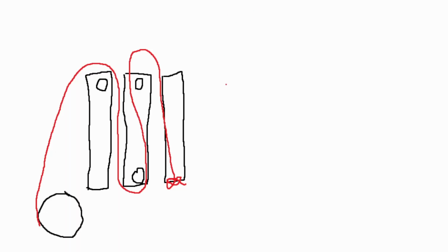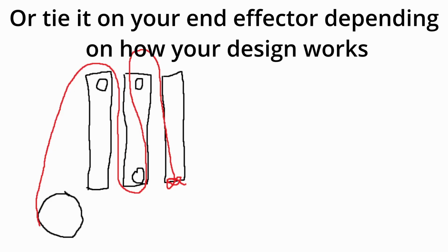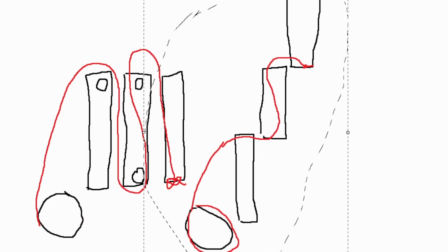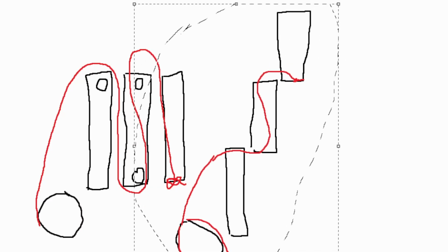Right here, you can see we have a fully retracted slide system, with this black wheel being the pulley, these small black circles being our bearings, and this red string acting as our string. So as you can see, this is the most complicated path it can take, or the longest path that the string can take. It goes over the first pulley, now at the very top of the first slide, because this is your base, not including any stroke length. And then you go on your next slide, and it wraps around the bottom one, across the top, and then when you get to your final stage, you tie it at the bottom, because that's going to be the bottom of the topmost layer.